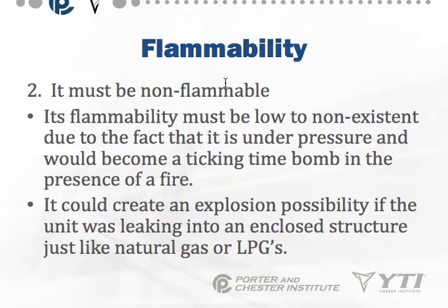You cannot have flammable refrigerants. Now, I'm going to talk more about a slight change to this, but refrigerants are supposed to be non-flammable. Its flammability must be low to non-existent due to the fact that it's under pressure and we could become a ticking time bomb in the presence of fire. It could create an explosion possibility if the unit was leaking into an enclosed structure, just like natural gas or propanes. Now, we're talking 2016, 2017 here.